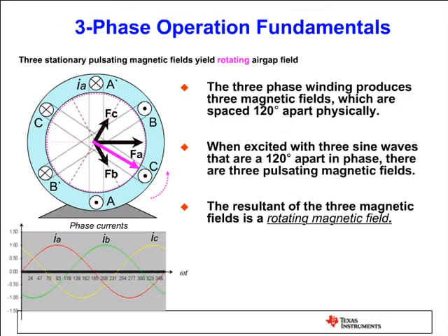Here I'm going to talk about three-phase operation. Now, as you know, in three-phase motors, PMSM type of motor, BLDC type of motor, induction type of motors, the stator has 3 phases and several slots, and the phase windings are distributed through the stator structure. Here, in this slide, the windings are not distributed. Instead, phase A, phase B, and phase C are shown as a single coil or turn, which is not indeed.